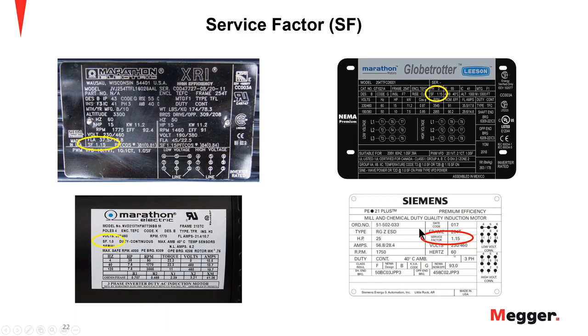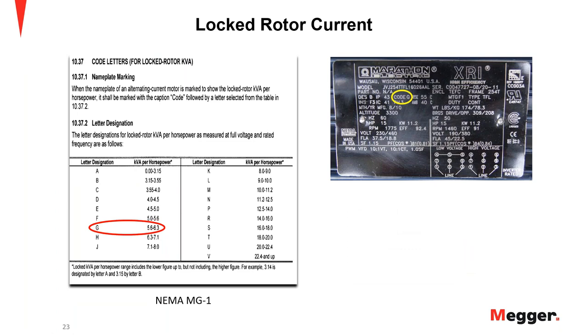And in some relay manufacturer information I was looking through, some will dictate that if you have a service factor of 1, they automatically tell you to calculate it at 1.05. But you need to look at the manufacturer literature for that. There are different cases for different scenarios, and this would be one of them. So I would definitely look at whichever relay protection you're going to apply and see what they recommend to do for a service factor of 1.